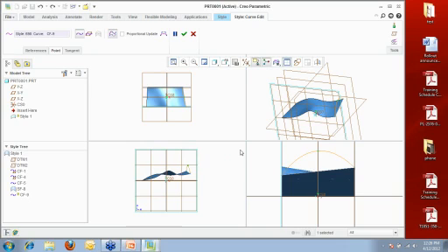One of the bigger problems that you run into with creating curves through points in the regular parametric tools is that when I go to tweak and manually drag and push points, if I drag this point this way, there's nothing, unless you specifically tell Creo Parametric to prevent it, from diving away from you. And so you could drag this point way over here like this, but until you actually turn the model, you didn't know that it dropped 50 feet away from you in Z depth. And it was always kind of a frustrating thing to deal with, okay? So when you're doing it this way, you can at least see and know that it's not moving in those other planes within the views that you have. Okay, go ahead and turn the views off.